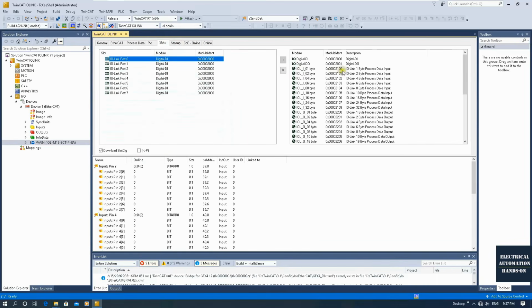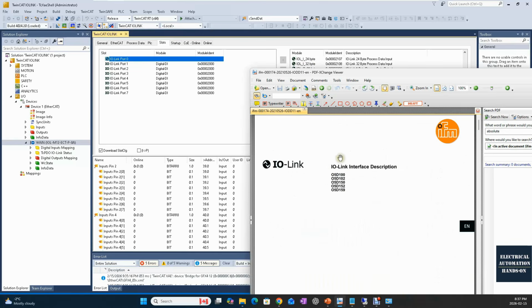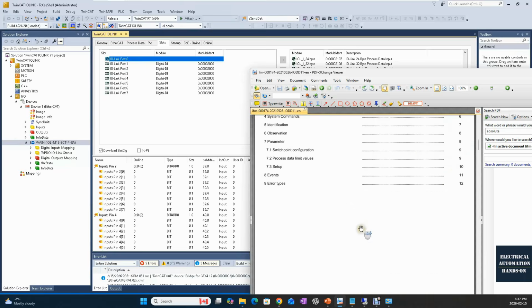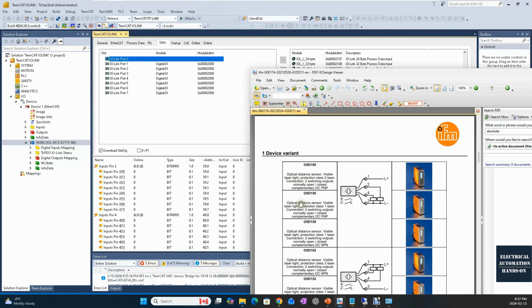And once we click here, we can see that for each port, we can configure it. Different brands of IOLink master would have a different configuration style, but they are quite similar. In this case, my IOLink device is connecting to port 0. So here, I will firstly click delete. Okay, by default, it is digital input. So I'm connecting the FM05D150, this IOLink device. And according to this device, this is the FM05D150, okay, laser distance measurement sensor.